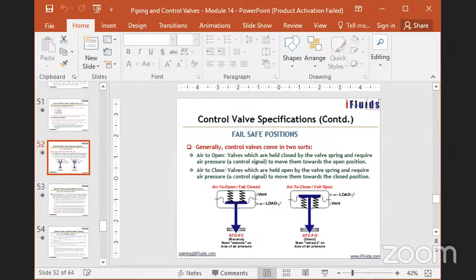Or you can use the flue gas to heat some other stream like steam, etc. So part of the flue gas is taken upstream of the damper and passed through the economizer, and the cold flue gas is put back in the stack after the damper. So the damper you can control to regulate the pressure drop in the furnace, and also you can use it for reheating the boiler feed water, etc. So we don't use this kind of valves in solid service. They are different.